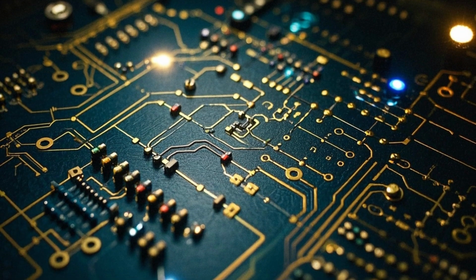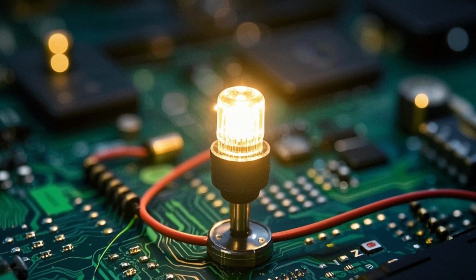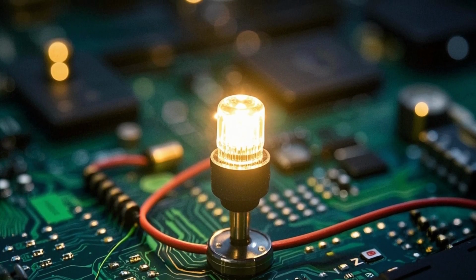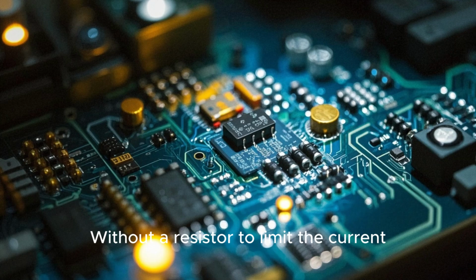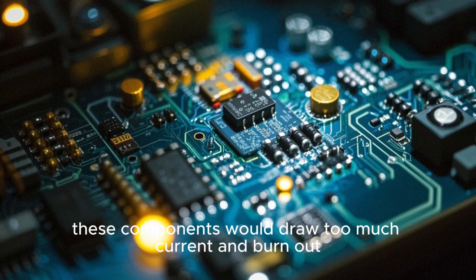Resistors help manage the voltage drop across different parts of the circuit. This is important because many components like LEDs have a specific voltage they need to operate properly. Without a resistor to limit the current, these components would draw too much current and burn out.